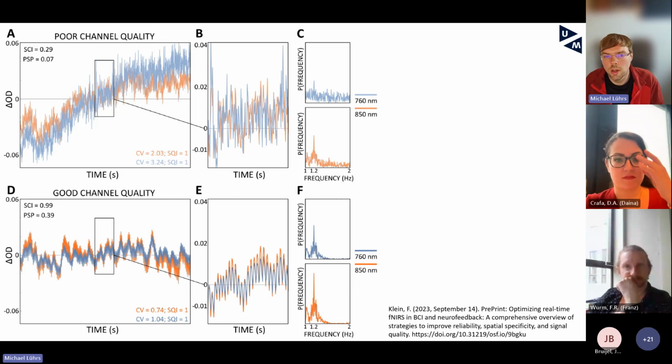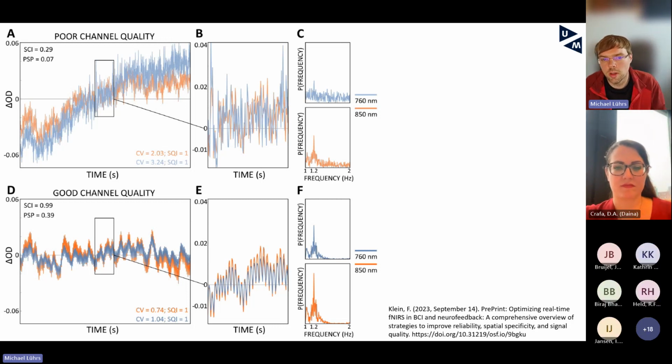That's totally fine. But you can also go one step further: if I filter the data and then look at the channels, and you still see that channels which are close by have a high correlation after you've done the processing, it means that this channel was still covering good information within the signal. So it is part of the whole pipeline to see if that matches. And looking at the frequency spectrum could be one potential way, but we will do this in the hands-on in a bit more detail.